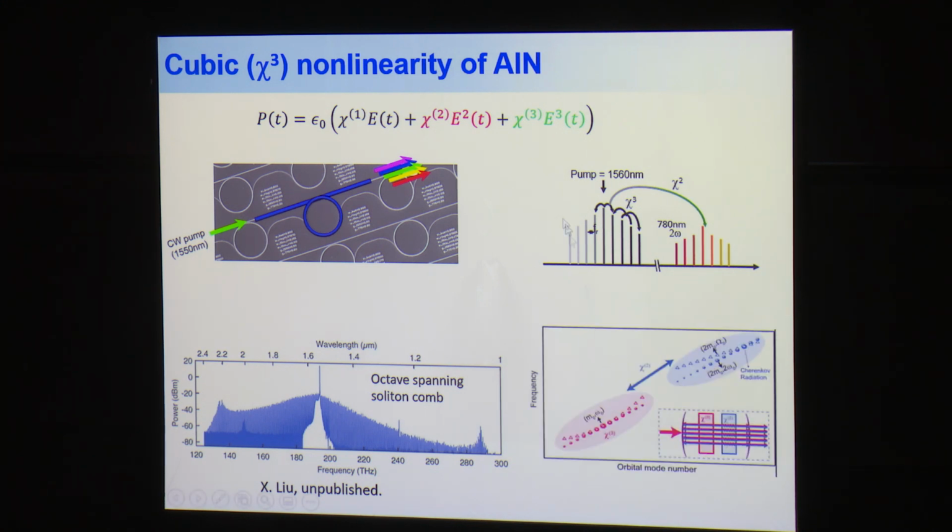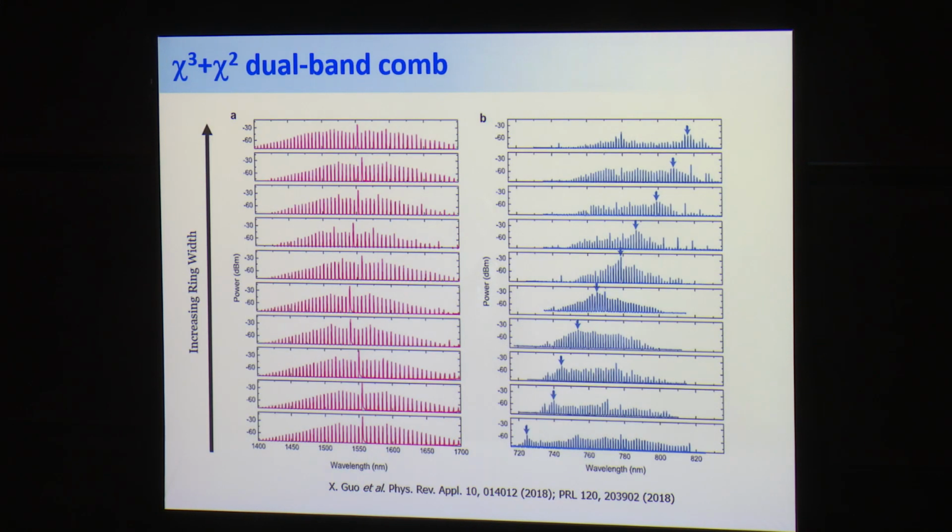As you can imagine, the phase matching and dispersion engineering of this device is really challenging, and you need chi-3 phase matching and chi-2 phase matching in the same device. We have not got there yet, but we have some success. With a narrowband comb, you can do that. So we engineered a device that has an enormous dispersion, very robust, with different widths of the resonator. You can generate an almost identical comb at 1550 nanometers.